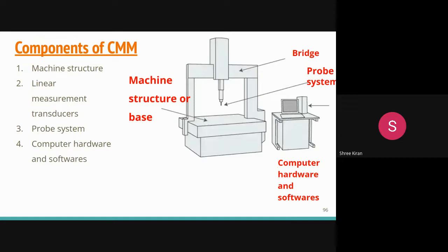Coordinate measuring machines are controlled either manually or by a computer. In terms of control technological equipment, two types are in use: manually operated CMM with computer-assisted data evaluation and reporting, and CNC CMM with offline programming capability and measuring data feedback. CNC CMMs have a high degree of automation and high flexibility, and are widely used.